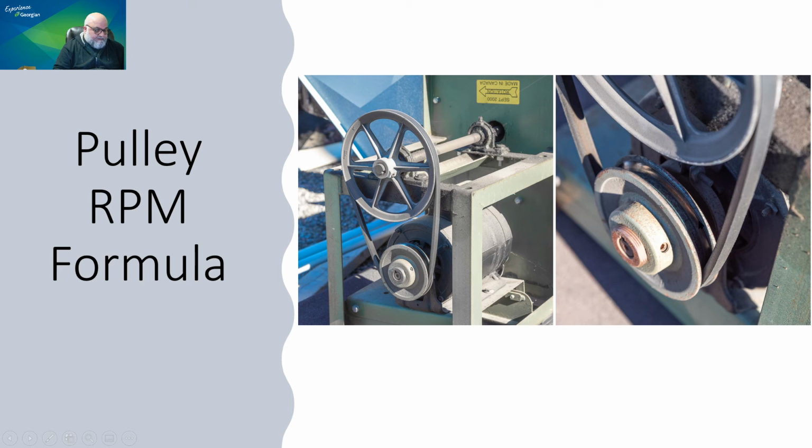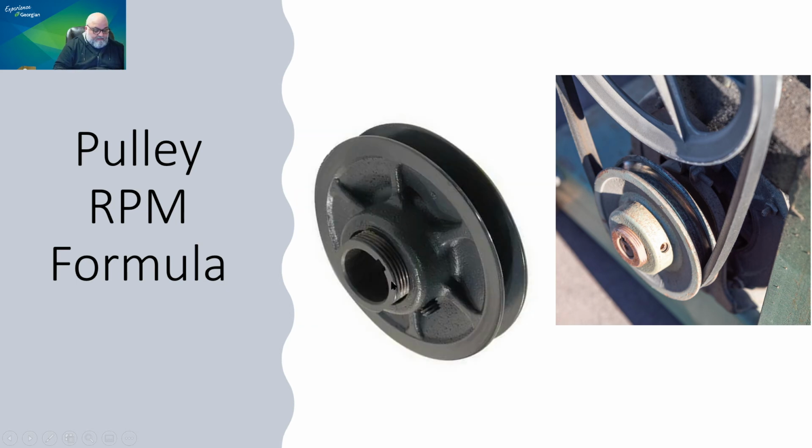And if you look at the motor pulley, something interesting is in here. There are threads where, if you undo this screw, you can rotate this part, this face of the shaft of the pulley, while the other face stays stationary. Let me give you another, maybe clearer image here. So again, when you loosen this set screw, this half of the pulley can turn and move. So if you turn it in this direction, it will move away from the other